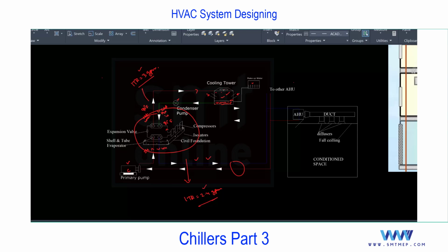Even in air conditioning also? Yes. Glycol has that capacity to hold the temperature for more time. Again, apart from this, for life of the system, if you use only water, like normally in our car radiators we are using coolant, not just water. But coolant we are using to increase the life of that heat exchanger. The coolant is not used to extract the heat. The water is responsible to extract the heat. If you use pure coolant in the car, that will not help to reduce the heat of the radiator. Water is a must. With the water, partly coolant is required so that the coolant will help to not damage that system, to reduce the oxidation.